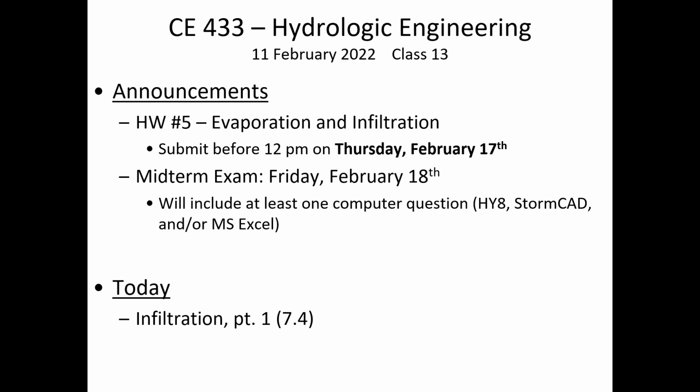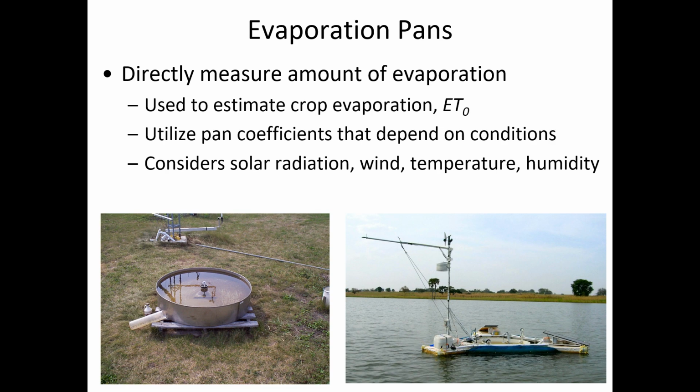Before we get into that, we just have to very briefly finish talking about evaporation. One of the ways that we can measure the effect of evaporation is by setting pans of water out and measuring how much of the water evaporates in a certain known period of time. Then, over the course of time, we can develop relationships between how much water evaporates out of the pan